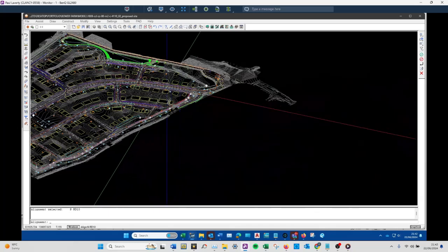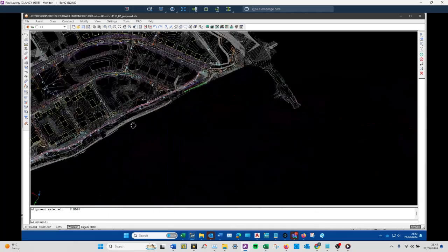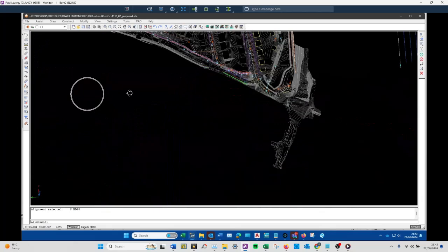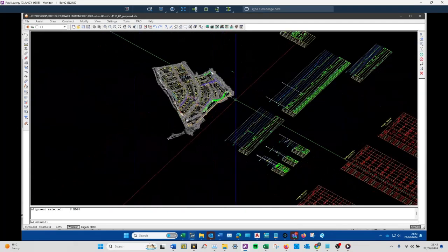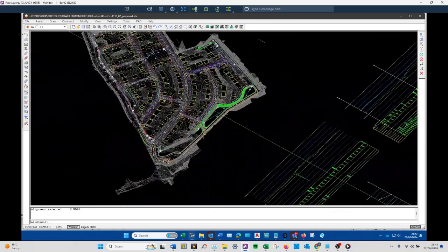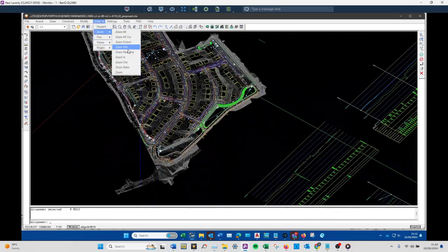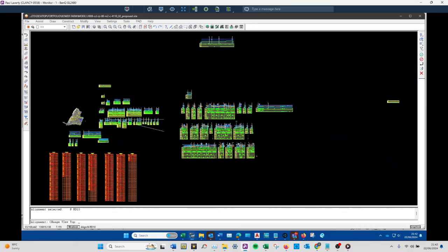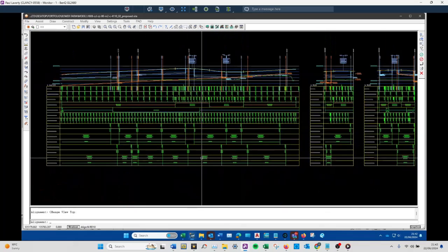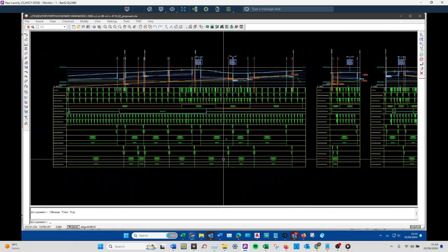So instead of trying to use that information that's in the XREFs and making sure that you don't delete something that some other drawing needed, or add something in that shows up in all the other drawings that you didn't want to add, and causes problems because someone prints it out and says, what the hell is all these circles and lines for? Well, that wasn't on that. The best thing to do is you have a folder for your PDS, any drawing you're going to use, you just bring it into here, edit how you need it, and bang, you bring it into your stuff and you do the design. So that's what that is for.